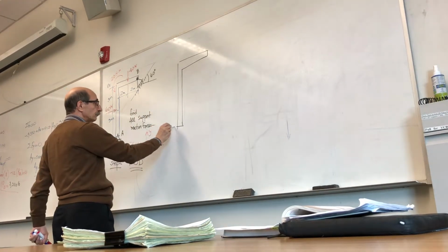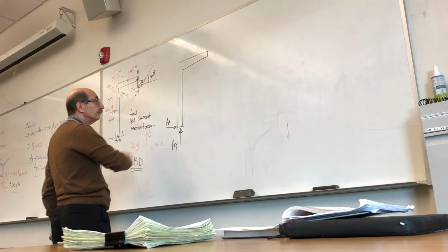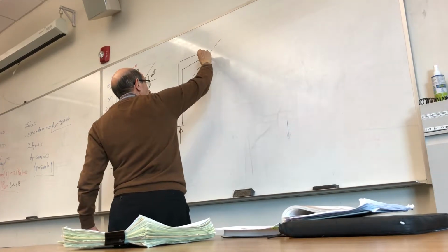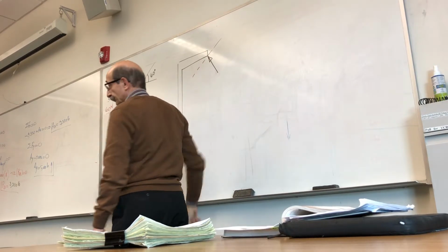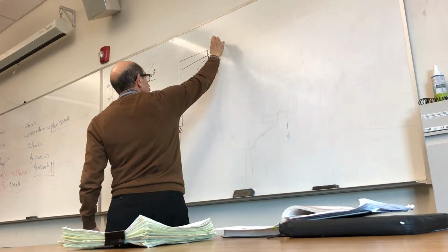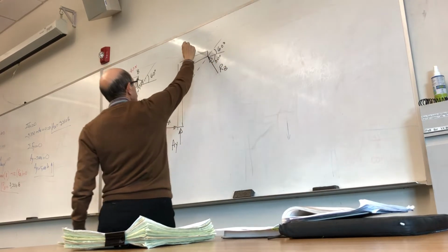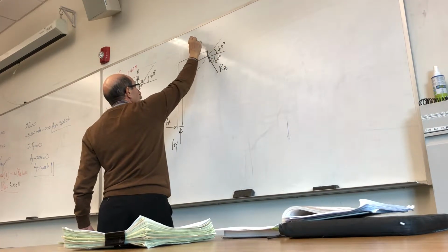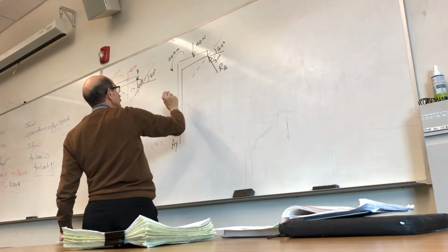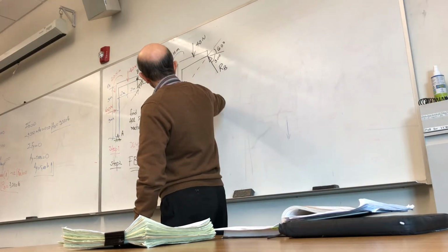This is the pin, so you have two unknowns. Again, remember, directions do not matter. Here, you have a force that does not allow motion in this direction. That's what that roller does. So this is 60 degrees, meaning this is 30 degrees, and this is R at B. Put back the applied loads, 40 Newton, 20 Newton meter moment, and 60 Newton force. This is the free body diagram.